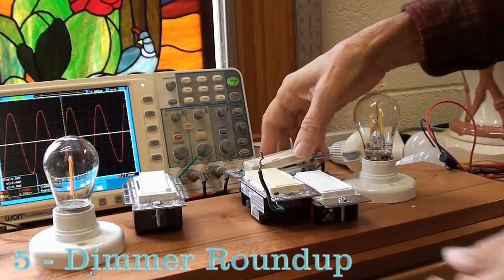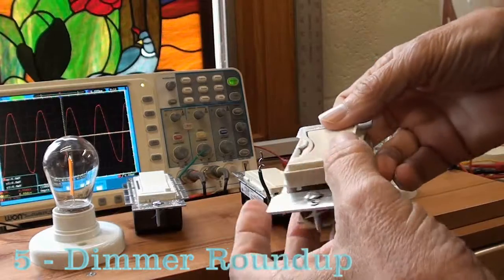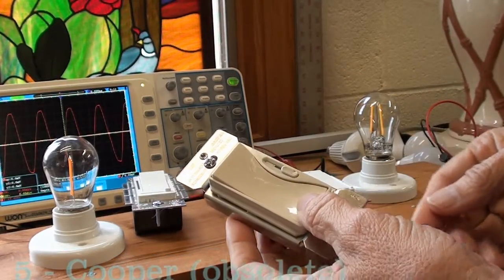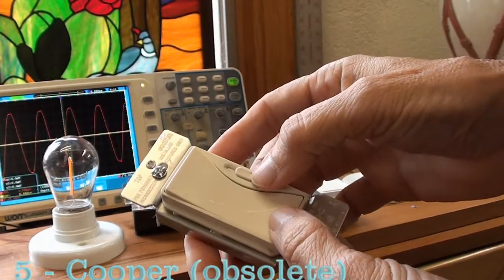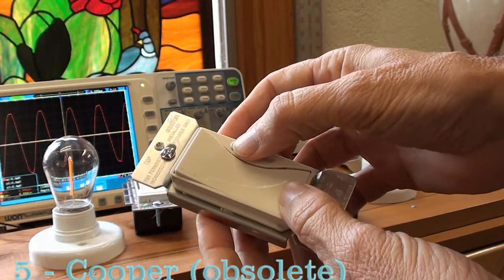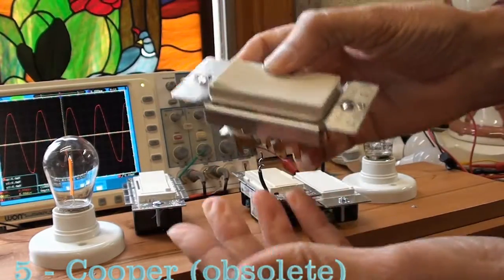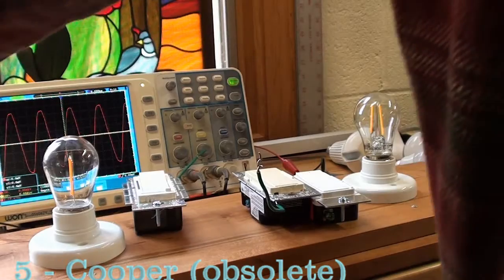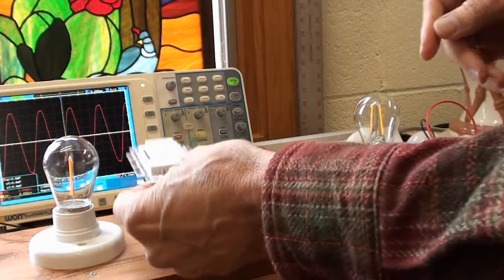Then we come to the only switch I didn't really talk much about, this antiquated Cooper switch. This one actually had one feature that all of the switches should have, and none of them do, and I think this is a discontinued one. When you went to full brightness, it actually had a switch that bypassed the dimmer circuitry and put the full AC on. So that's a feature that every dimmer switch, in my opinion, should have. None of them do.